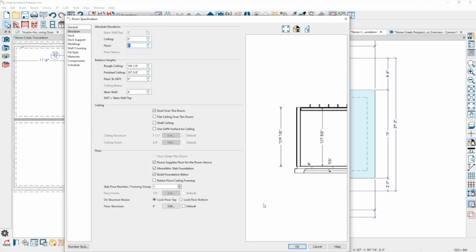No, wait, you've already defined I want the existing finished floor to be the same elevation as the new finished floor. Right. And now you're changing it. Right. So I would raise, because the existing condition is your floor joists that are already in the field, sitting on the stem wall. So that's going to raise that floor up, give it a number, 15 inches or something, right? Okay. On the left side. So on the right side, I need to raise this floor up that same amount.